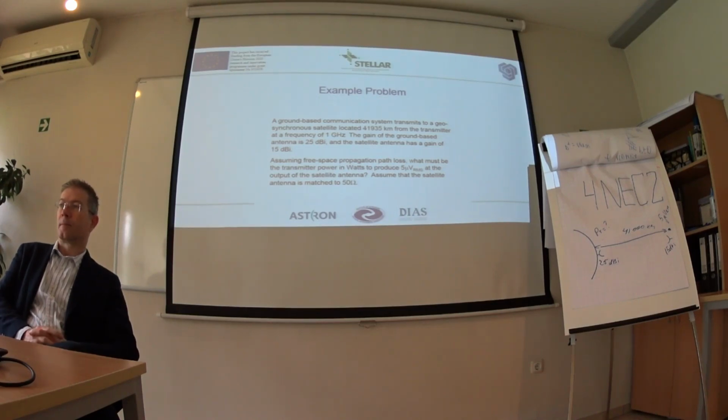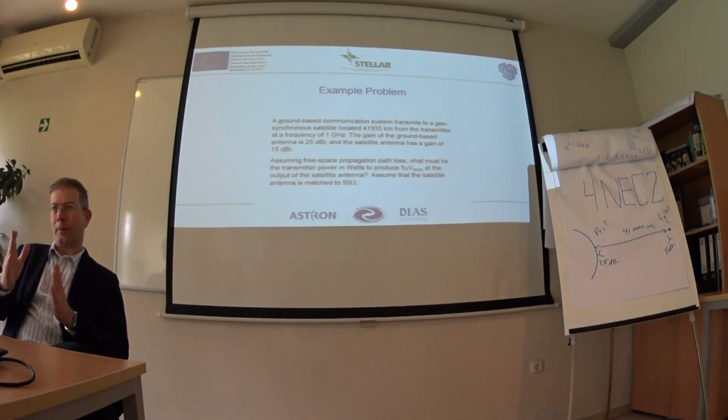This is the resistance at the bottom of the text, right? 50 ohms. Yes, it is the input impedance of the receiver. I will give you a hint. Knowing the input impedance of the receiver and knowing the voltage that needs to be produced, we can calculate the power that we need to deliver to this input in order to produce this voltage. You know, power, impedance, and voltage are connected.